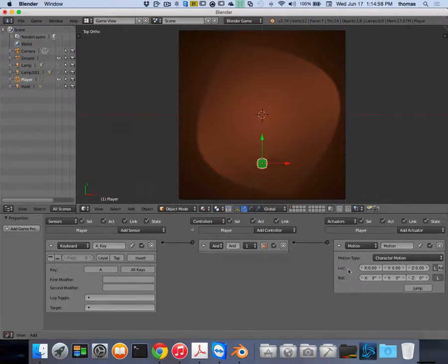So if you notice the location, I want to move it to the left, right? Because it's negative, it'll be negative X. So I'm going to just use this negative 0.1 Blender unit. To test this, if I press the P key right here, I can literally press the A button. And if I've done it right, it's going to move my object to the left, see? Until it falls off the screen and is gone, right? Escape gets you out of play mode and back into regular object mode.